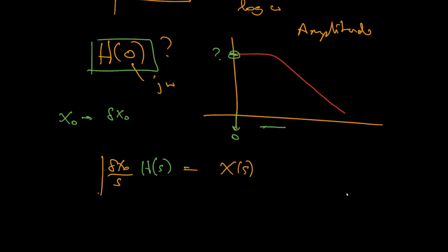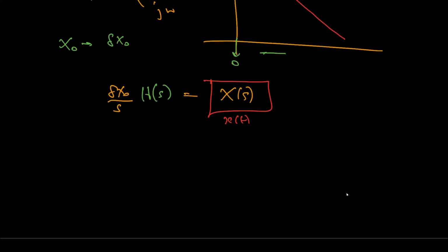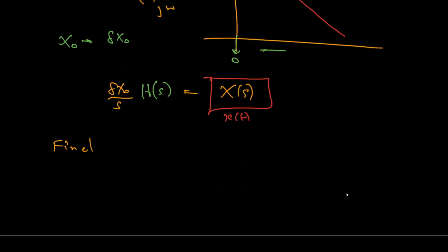All right. Now, what is the value of X at steady state after I've done this step input? Well, the way to work that out, of course, is to use the final value theorem. This is why I was confused with the final value theorem. Remember, this was used to compute steady state directly from the transform without going via the time domain.